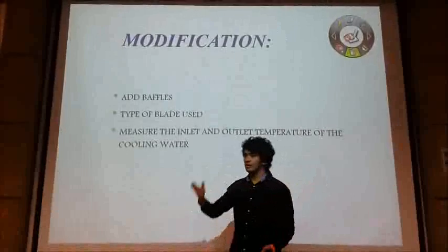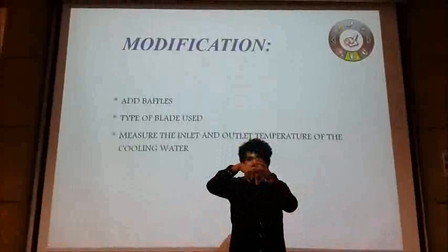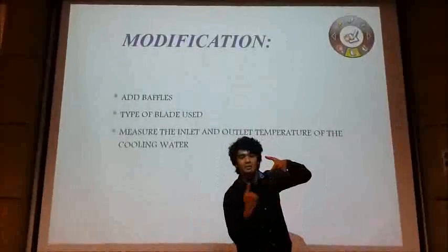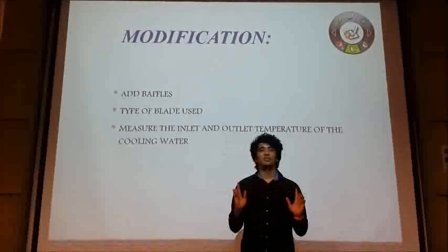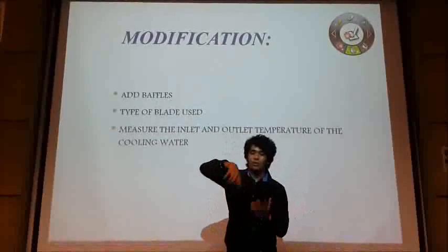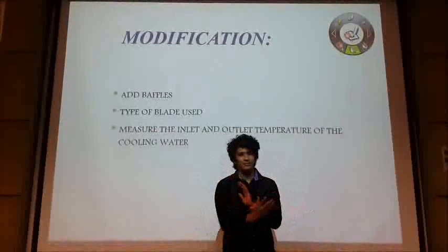So what we can do is to add a bigger blade. The blade should be placed downwards outside of the cooling coil and be spinning on the outside there. So it could be almost touching the sides of the reactor. In this case, the whole reactor will be spinning, the whole fluid will be spinning almost at the same speed.